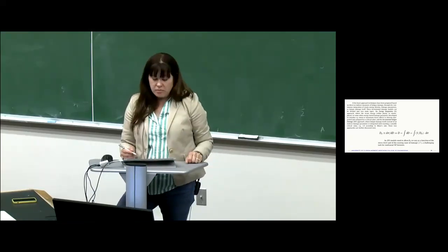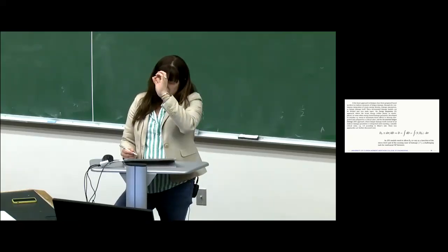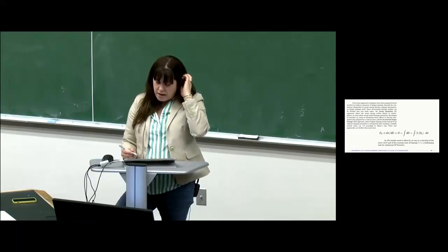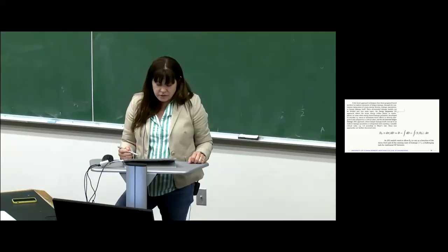And so they then go on to develop this model. And they talk about other models as well, because if you're throwing out the cycle model, then you might be going to something that talks about local approaches, right, that talk about just that surface and just that crack. And so they talk about two main types. So one is the energy integration approach, and they talked about this as being insufficient in the introduction, or they hinted at that, where the strain energy, either plastic or elastic-plastic, or some other energy-based damage parameter, is directly integrated and compared to a critical value. Okay?